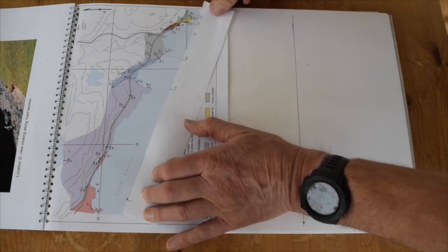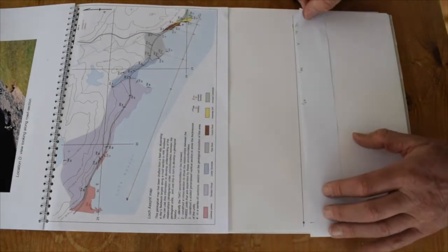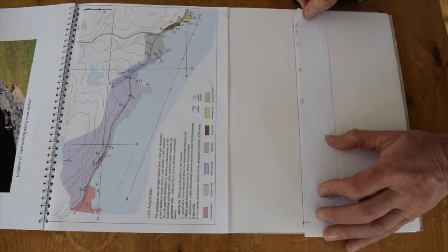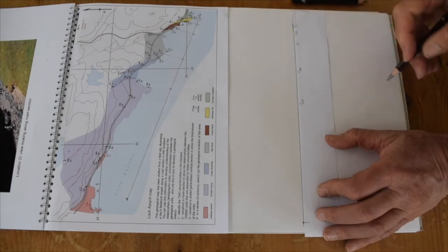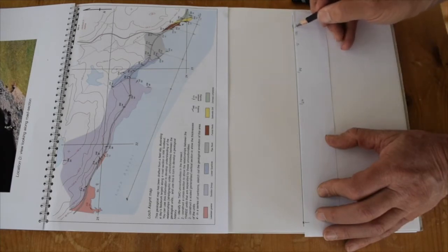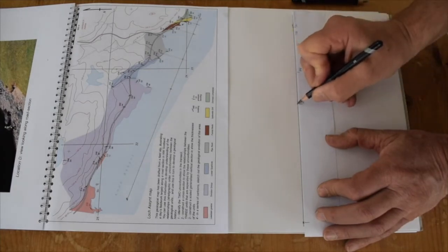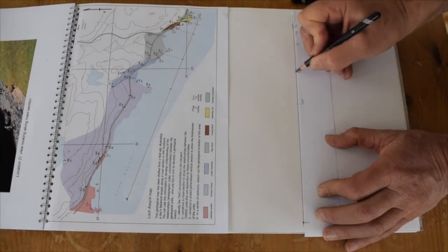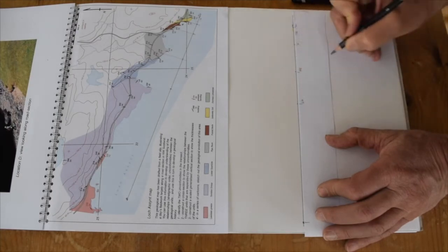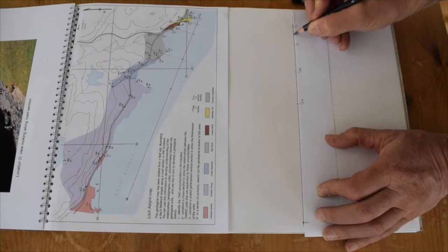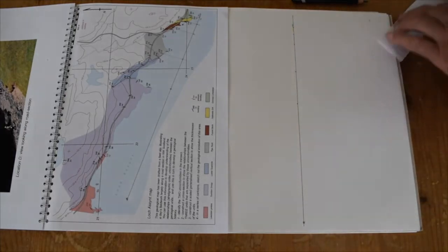Take that information, transfer it across. So here we go, line it up with a reference point. That matches where we had it before, the Saltarella grit Durness limestone boundary. There's the lower quartzite base, there's the pipe rock base, there's the fucoid bed base, there's the Saltarella grit base. Let's put some colours on.